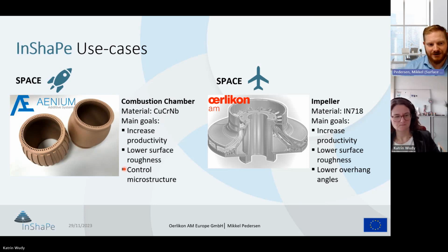By printing this alloy, they can get to a very specific microstructure state that really balances between the conductivity that is needed to survive the heat and the strength that has to be in the part as well, doing this very intense hot fire process that is for a combustion chamber. And this is something that could be achieved only through AM. But today, the sacrifice there is productivity.